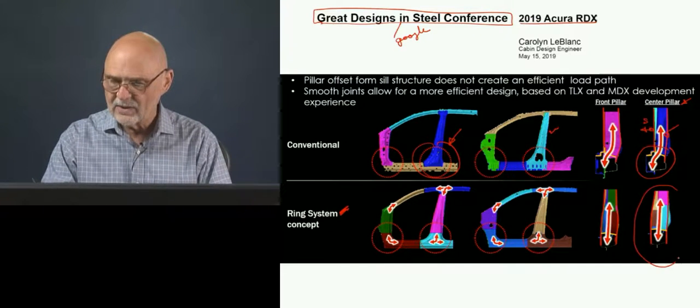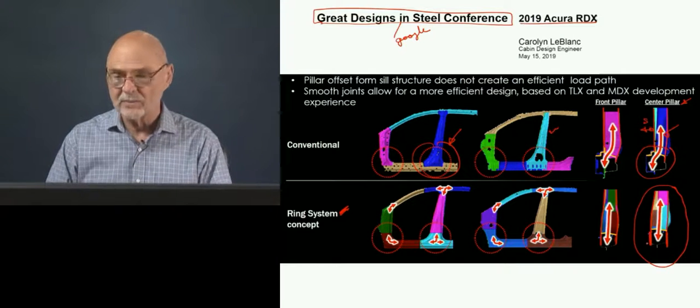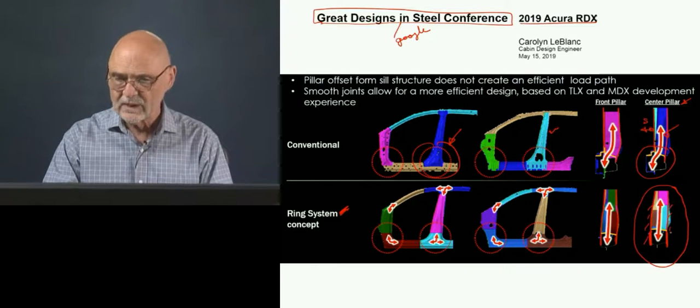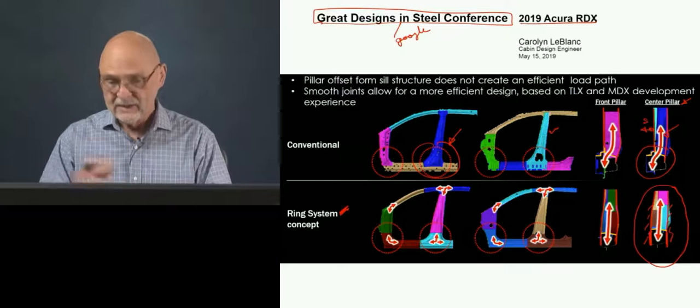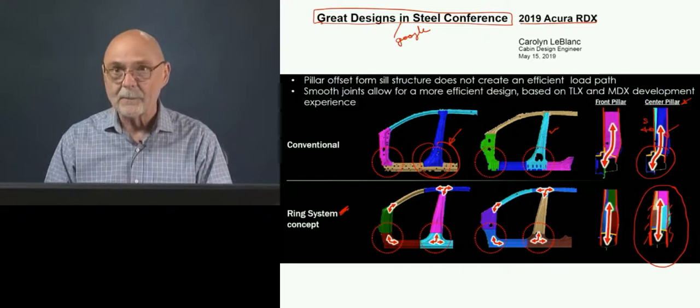And then here is their new version of this concept. You can see right here that what they've done is align the shear planes for the B-pillar and the rocker. So the exact good principles that we talked about, very difficult to achieve like they have done here.